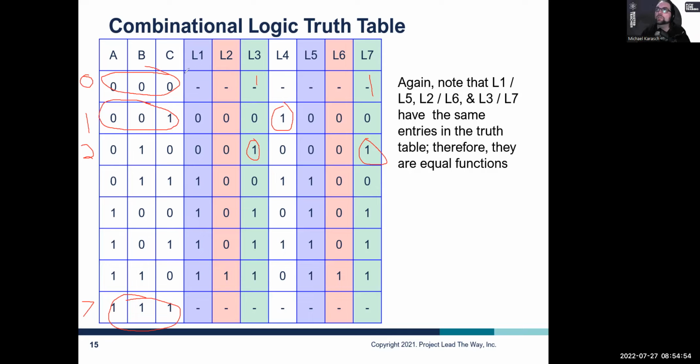And so we call this a don't care condition because we don't care what happens there. You could light them all up for all I care. You could light up half of them. Doesn't matter. Same thing down here with the 7. We don't care. In normal operating procedure, our die will never, ever show a 7. So we don't care what happens on the 7.